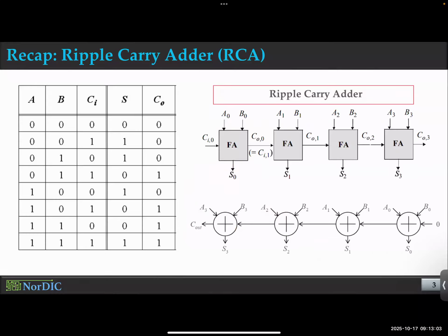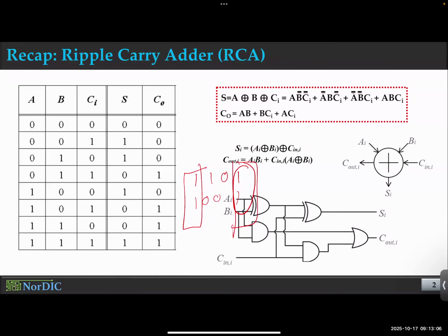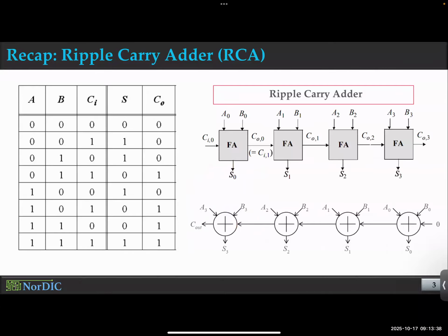So the circuits that we are designing are for a single bit, not for the entire number, as you can imagine. The interesting part about adders is once you design a bit slice, you could just repeat it as many times as you need. If it is a 4-bit adder, repeat it 4 times. A 16-bit adder, repeat it 16 times. That's the easiest possible scenario. But there are more involved adder designs where we collectively design the circuits. Instead of designing bit slices separately, we could always design blocks like 4-bit, 4-bit, 4-bit, and so on. And we'll see an example like that in this lecture.